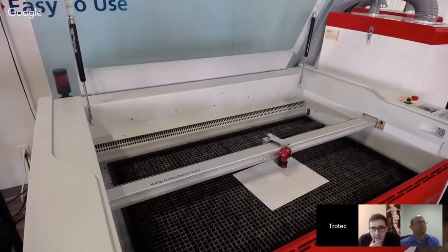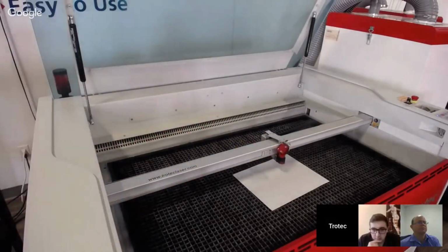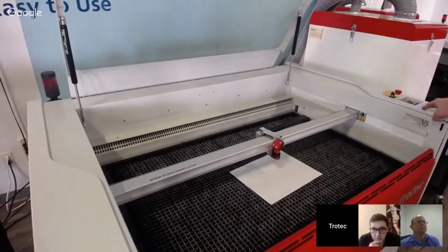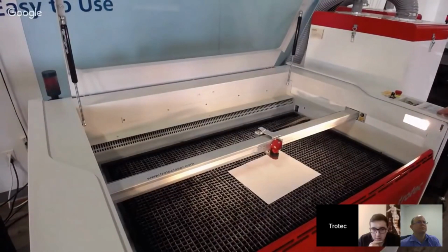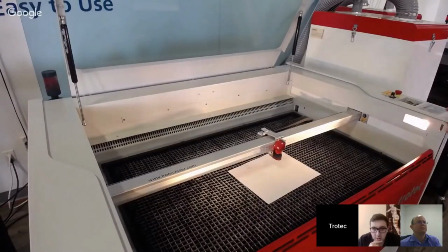Wait, Anthony, sorry, before you go back, can you show them the keypad as well, that you can move the head with the keypad, not just manually? Yeah, we can show you that. So right now our laser is in standby mode, which allows us to move this around freely, which is great. Or as Lev was saying, you can come here and take it out of standby mode using the power button. And now using your D-pad, your directional pad on your laser, you can move your laser like so. Yeah, and you want to make sure not to move it manually when it's not in standby mode. That's correct.